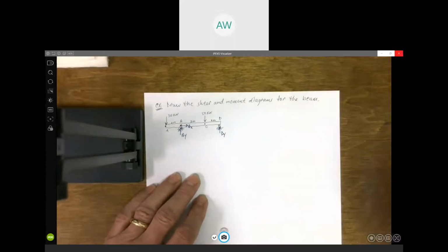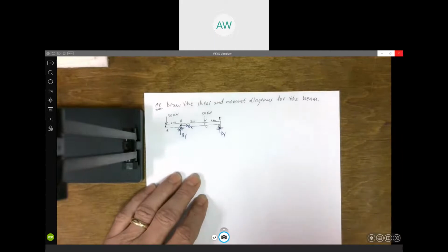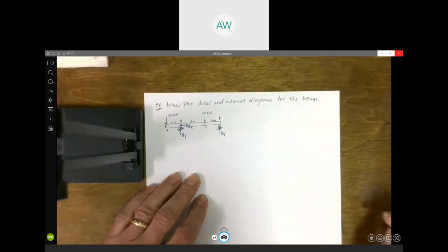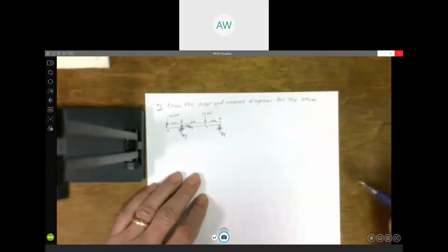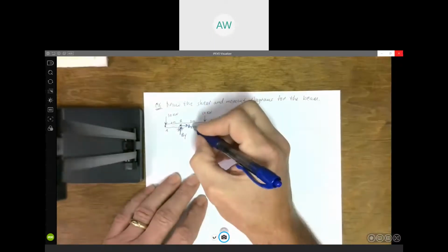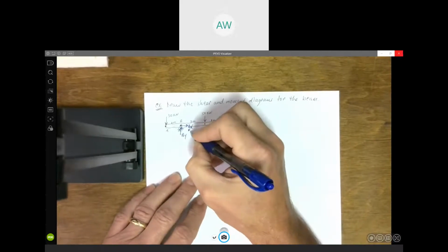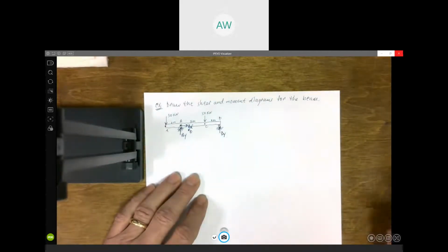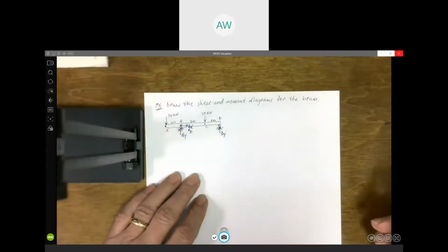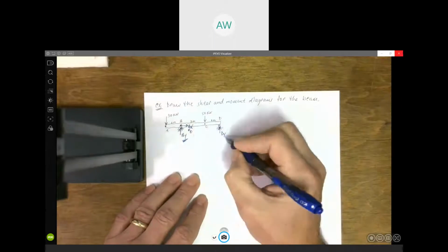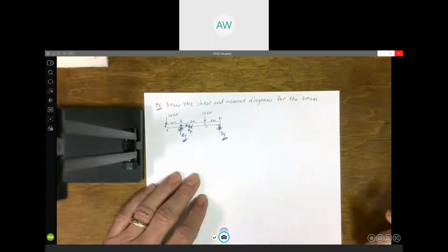Now, we don't have any other forces in the x direction. That was the assumption I mentioned a minute ago. We're assuming at this point there are no axial loads. The only two applied loads are vertical. And so just by observation, Bx is going to be 0. There's no horizontal force needed at that support reaction. So we need to find By and Dy.